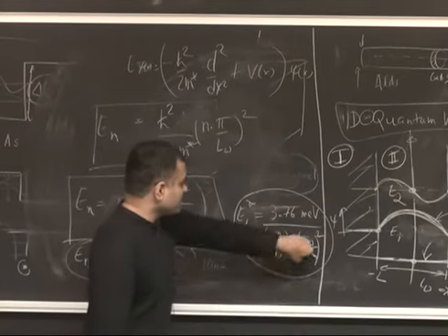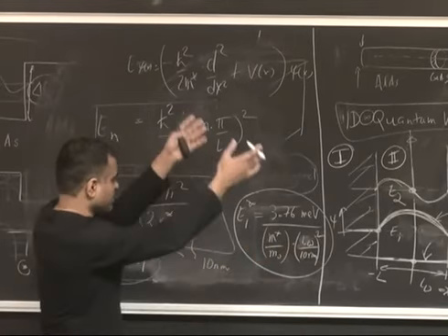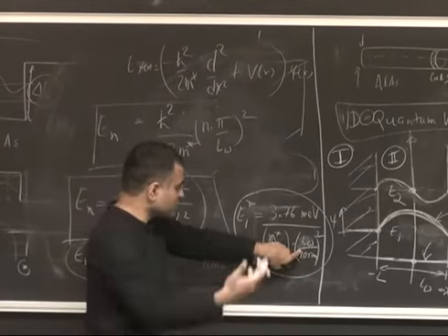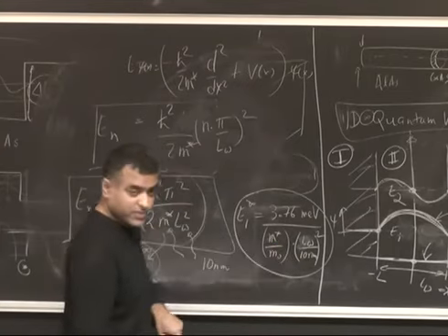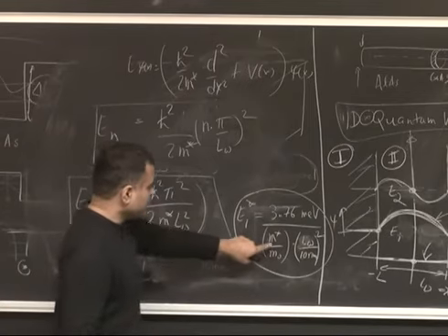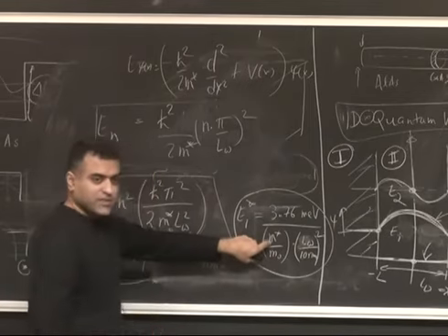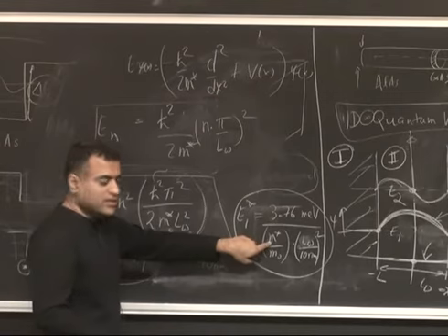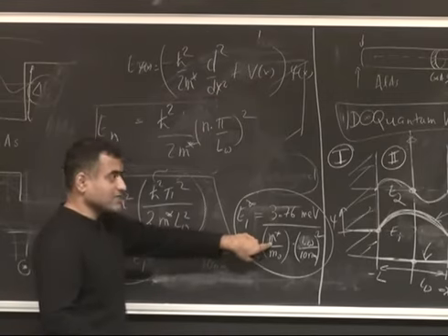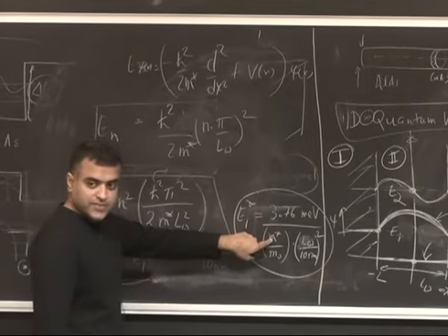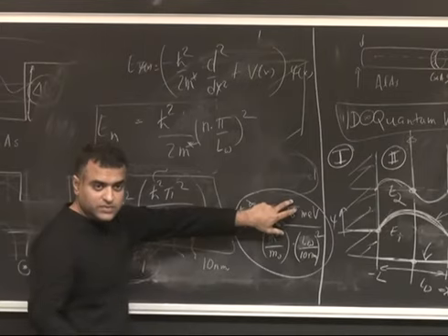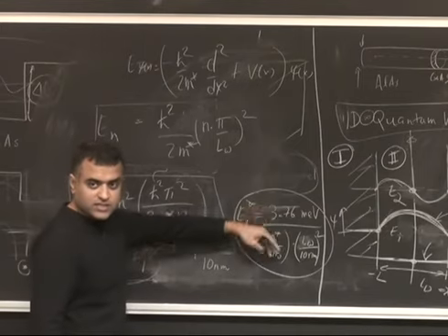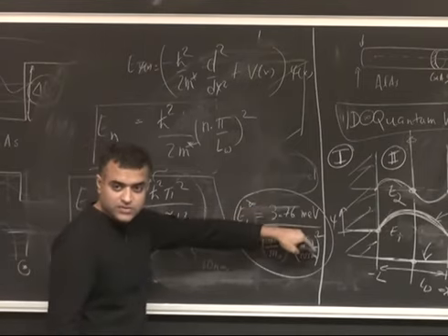This is a result of the parabolic band structure. If you don't have parabolic, you won't have square, but most semiconductors do have parabolic bands, so this is very important. Similarly, most semiconductors do not have an effective mass of 1. If you look at, say, gallium arsenide, it's 0.067. Gallium nitride, 0.2. So that factor will bump it up by a factor of 5 or 10 or so as well, right? So it's very sensitive to effective mass and very sensitive to quantum well width.